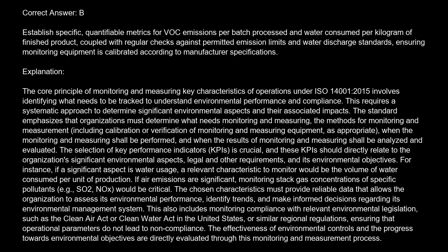The correct answer is B. Establish specific, quantifiable metrics for VOC emissions per batch processed and water consumed per kilogram of finished product, coupled with regular checks against permitted emission limits and water discharge standards, ensuring monitoring equipment is calibrated according to manufacturer specifications.